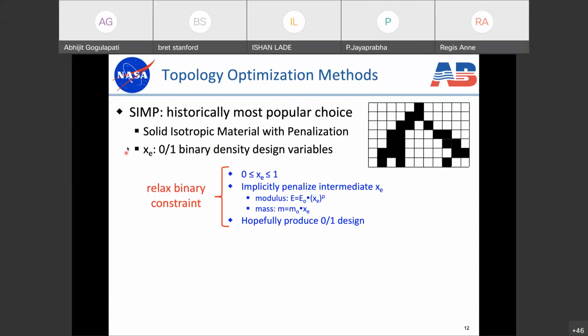So rather than forcing all of these design variables to be 0 or 1, we allow them to continuously vary between 0 and 1. So now we have a design optimization problem with a large number of continuous design variables, and that falls well within the purview of gradient-based optimization. The only problem with this idea is that the optimizer is no longer trading in strict values of white or black. Right now it's wading through a design space where it could have shades of gray as well.